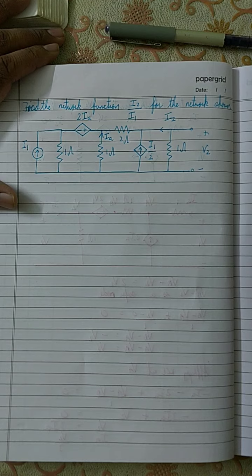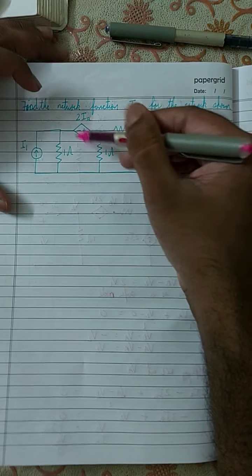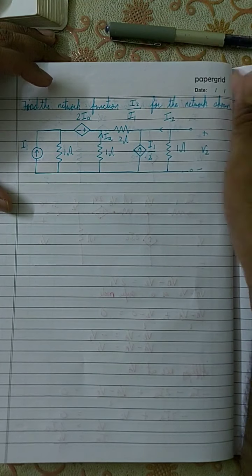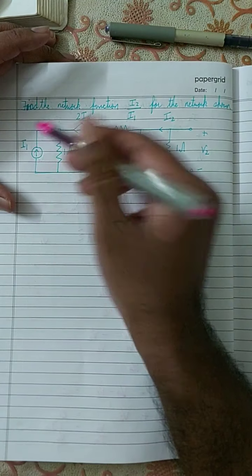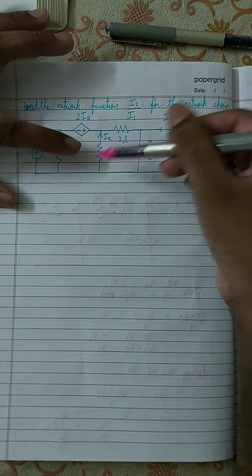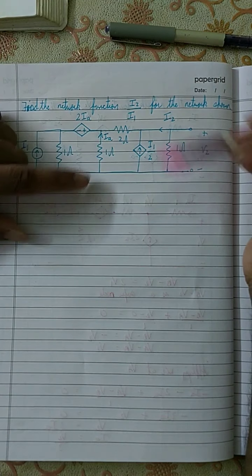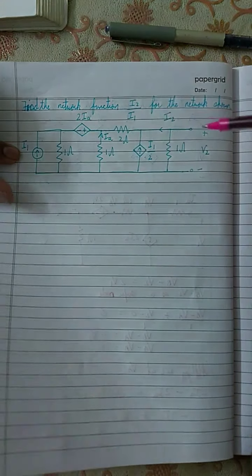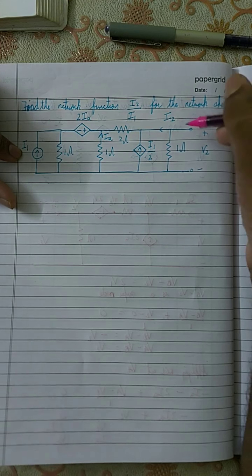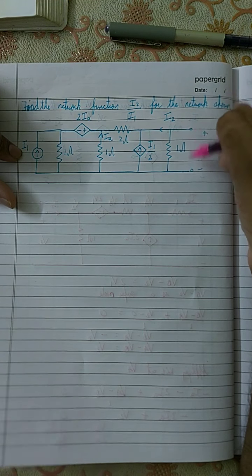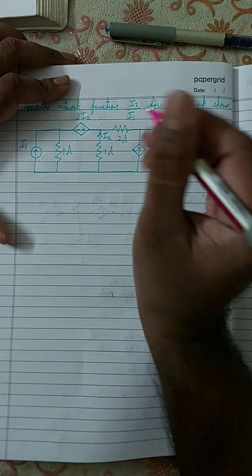Okay, so here in this question again you have a dependent source, which is a voltage source, so therefore again this will be a supernode. There will be a supernode in this equation, and that's it, there's nothing else. So here you have I1 over here, 1 ohm, here 1 ohm, another 2 ohm. This current source is I1 minus I2. Okay, so we all know what is I1. This is the current I1 over here, and here you have I2. And if this is I2, then you can say that the current over here is 0, right, because this mesh is open. So let's redraw the circuit in its Laplace transform.